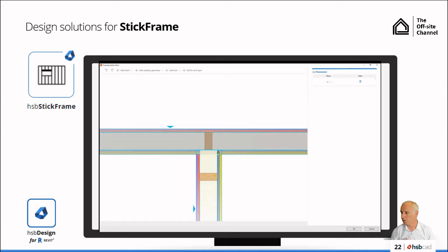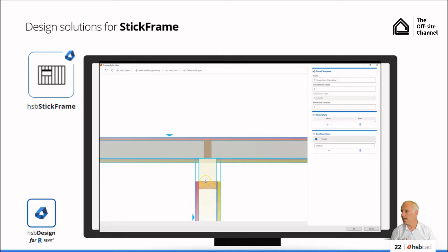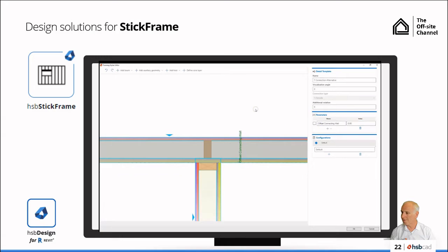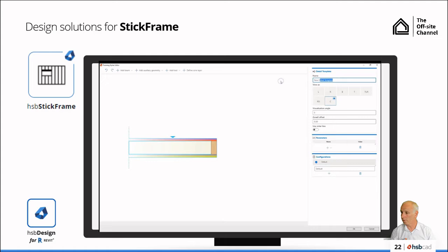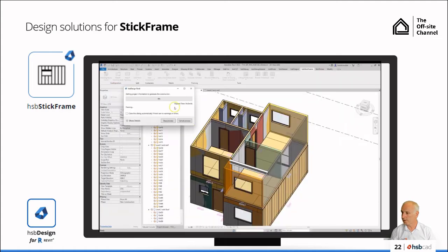Precision is important here, so we'll probably want to be able to stretch things and move things back accurately, and tolerances, for example, might be key here. How often do you want to have that 1-2 millimeter step back from the edge of the panel because of tolerance in this case? So this is a fully integrated detailed system where it will allow you to graphically define all your connection details yourself, and this can be done for all T-junctions, corner connections, and around openings, to create those details as you would desire.